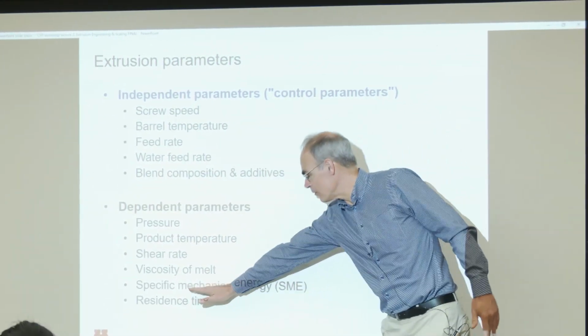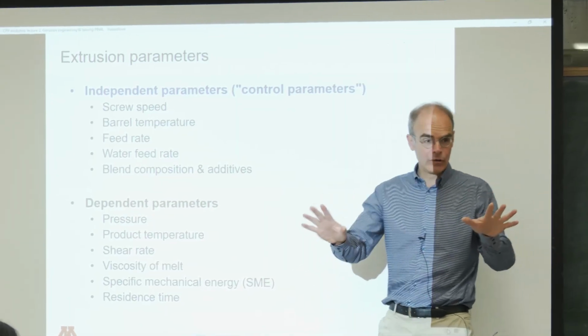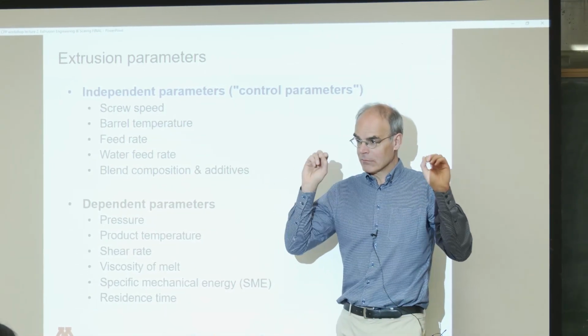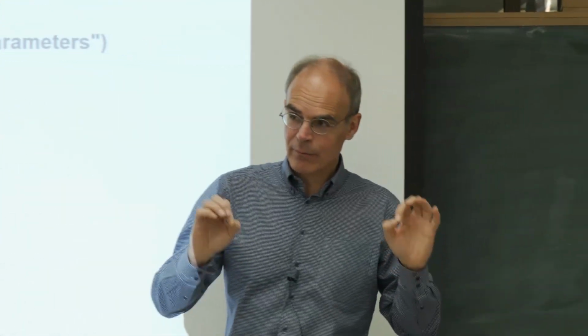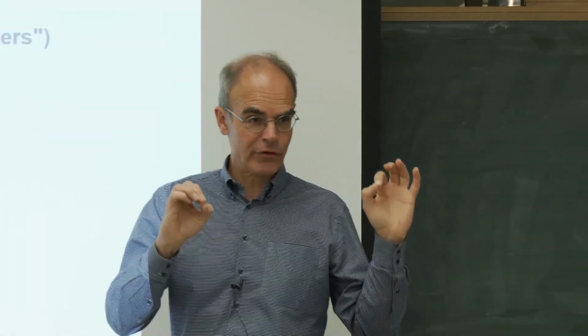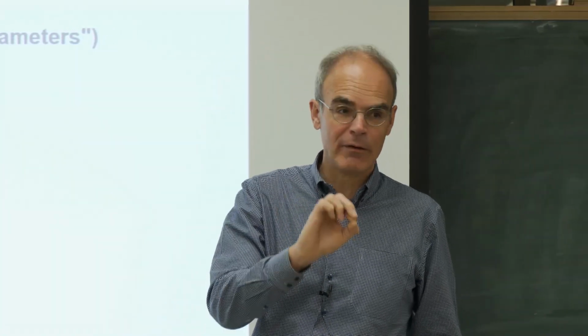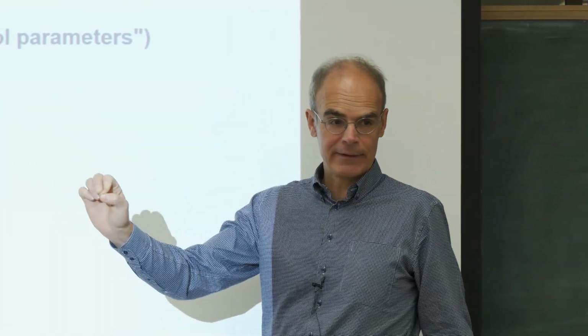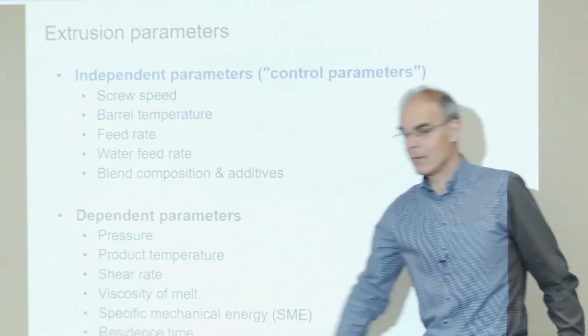Then a parameter we spend time on today, the specific mechanical energy. That's the parameter I want you to really know. Because this is really important in monitoring extrusion processes, and is, I would say, the broadest accepted parameter that we use in extrusion scaling. Yeah? And then the last one, a bit surprising maybe, residence time.